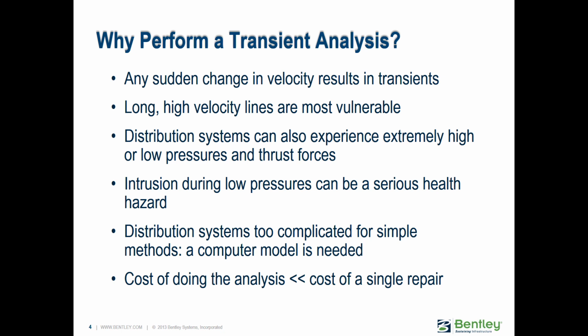And for that reason, you want to do a transient analysis to make sure that the result of that surge or water hammer event does not cause pressures that would possibly break your pipes, burst your pipes, exceed the pressure rating.